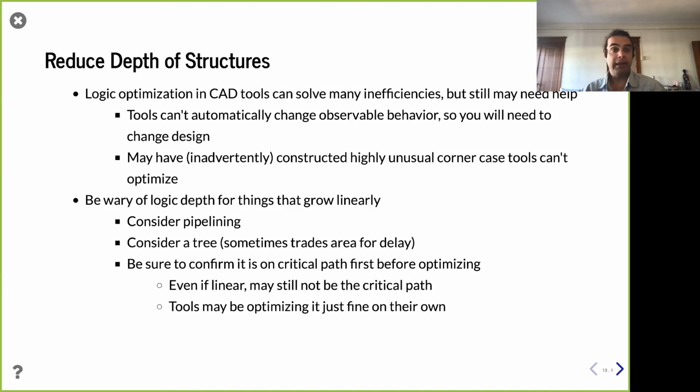But either way, like I said, my advice has always been: close the loop, get something running, get it correct, then worry about optimizing. And when you're optimizing, not only should you be starting from a correct design, you should also have a way of measuring it, and you should be convinced that this particular thing you're fixing will yield benefit if you change it, right? For example, if you're looking at a path and you think, this is a really high delay path, I should go fix this, but it's not currently your critical path, don't touch it yet, right? Because realize that it doesn't matter. The critical path is what matters. Now, perhaps after you optimize 5 critical paths, that one then becomes your critical path, and that's when you deal with that thing, right?